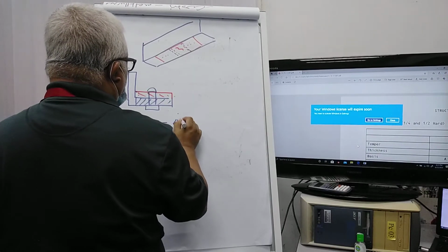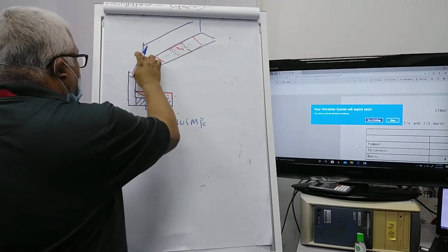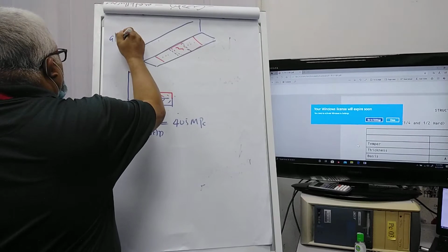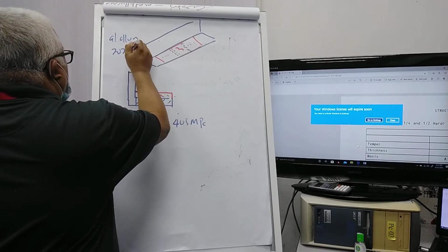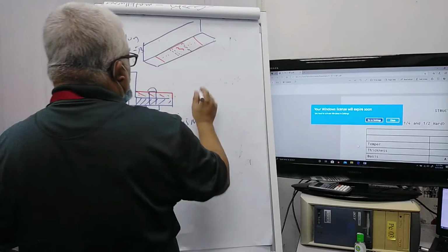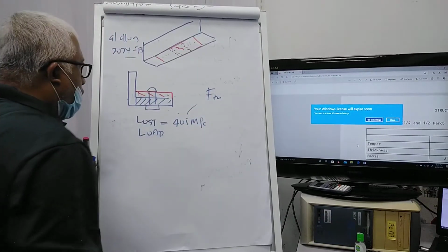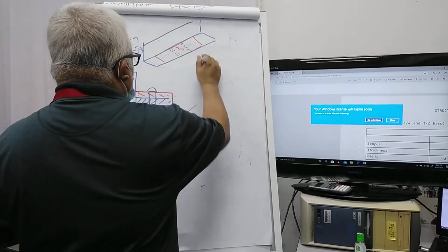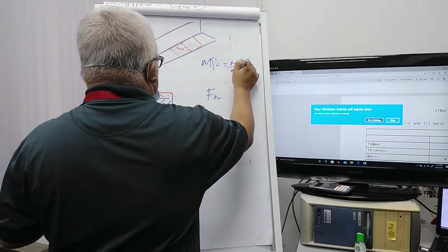We have agreed that 405 megapascal is the strength of this material here. This one is aluminum alloy 2024 T3. So the strength, the FTU of this aluminum alloy 2024, is 405 megapascal. Megapascal is also Newton per meter square.